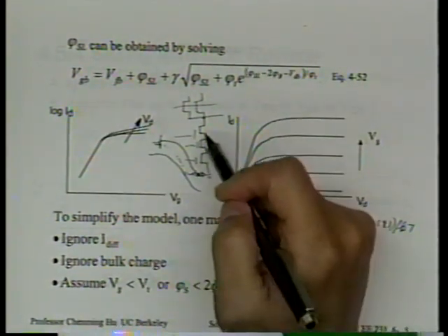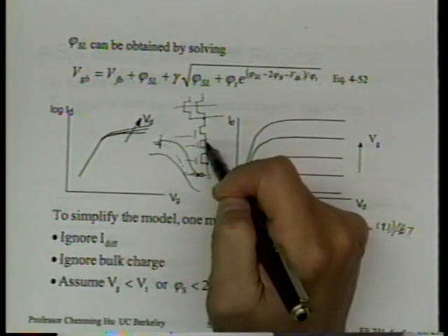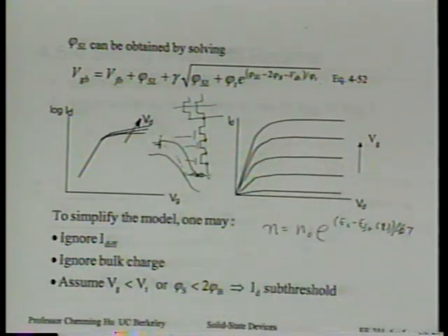So in this circuit, we have three sources. They are at a different location, so there's no way for them to all be tied together, to be all shorted all the time. And yet only have one body, because they're all made in the same wells, in one body. So just for this reason, source cannot always be tied to the body. Not that we prefer it for some reason, it's just we cannot. Right? It's necessity.